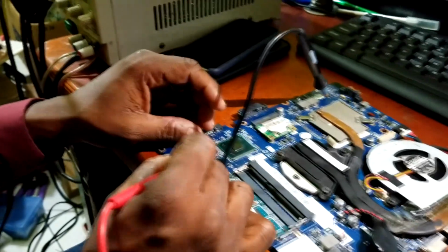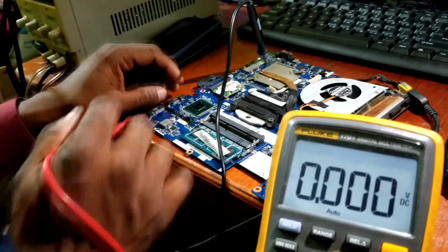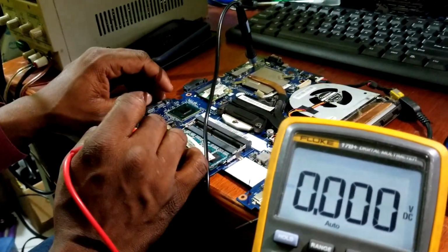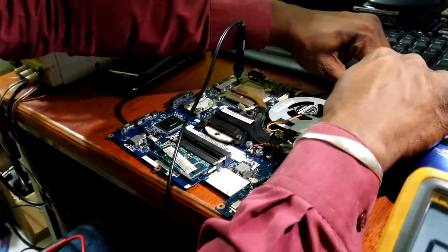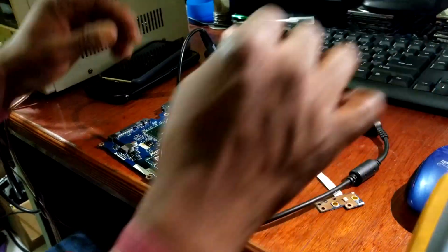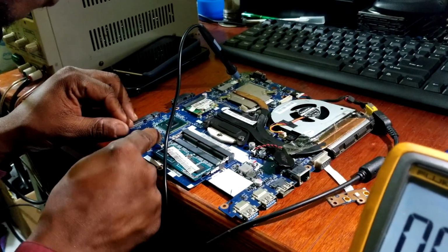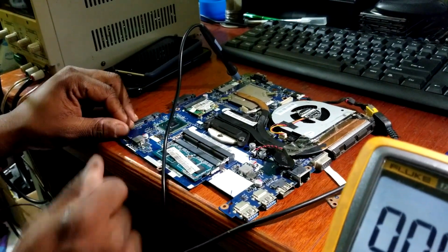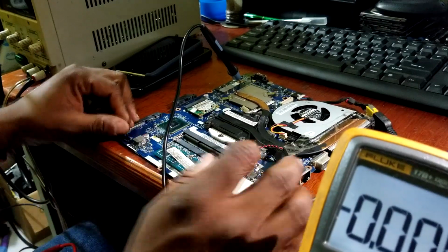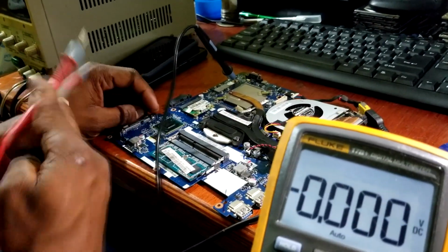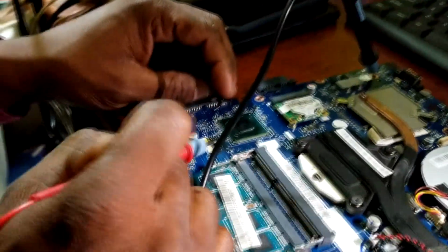is going to be read. All right, so we're going to check if the CPU is reading the BIOS. Let's see if the BIOS is being read. Next, we are going to check. I'll plug it out. Oh, I see. All right, so we're going to check the chip select signal. Remember, the BIOS chip has a chip select signal here, so we can use it as a measuring point to check with our oscilloscope.